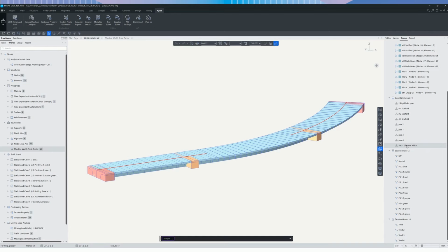If I ask to show what it is, the program will highlight those sections, because the largest section with 100% is positioned in the middle span, and other sections are put in those boundary groups, and now it's highlighted like that. Boundary group is needed to be able to operate the width of section in relation with the stages of construction.